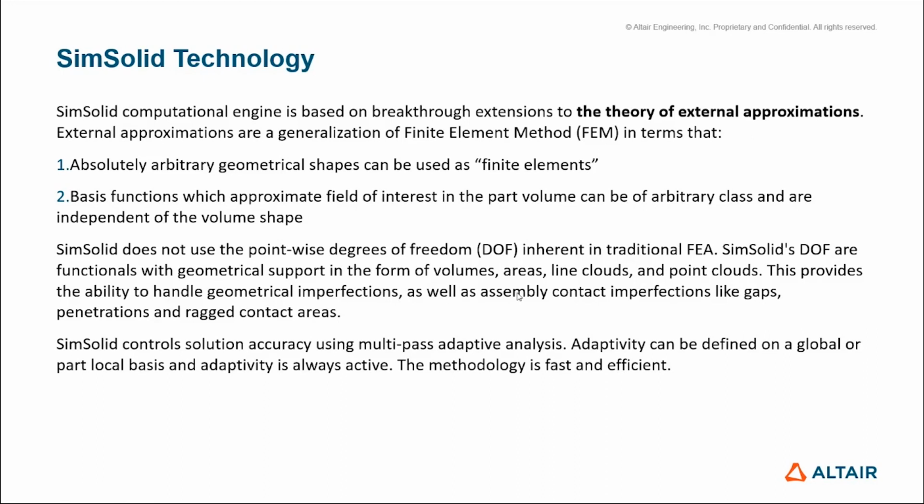Again, as I said, it can cater for gaps, penetrations, and very ragged contact areas, quite intrinsically. SimSolid controls solution accuracy using multi-pass adaptive analysis. Because what you need to do, and I'll show that now, is solve for the approximate error at the boundary conditions.